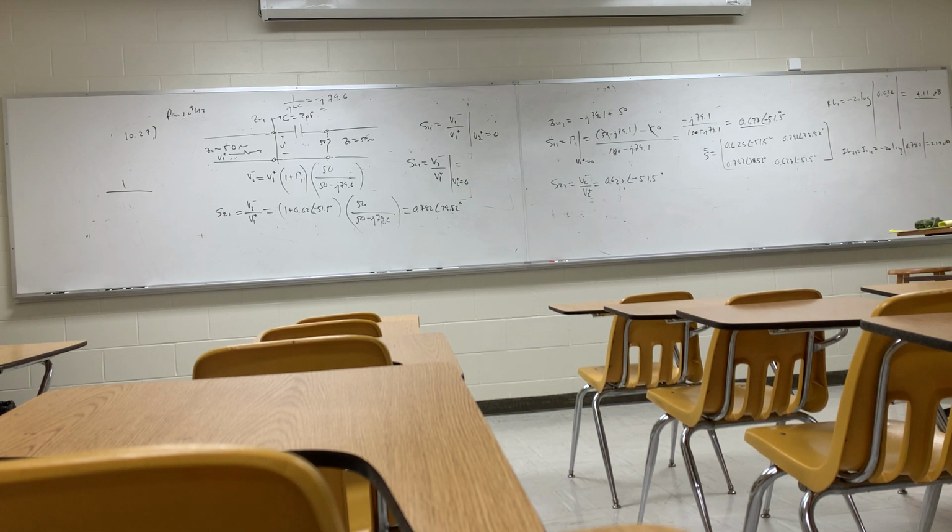Now go to the next one. That's B. Take a look at that. Is there any way that voltage from port 1 can get to port 2? Immediately you know S21 and S12 are 0. There can't be a forward or reverse voltage gain. Are you with me? Now, when you look at S11 or S22, look at that one carefully. What's the input impedance to port 1 or port 2? Infinite, right? It's an open circuit. You all see that? There's nothing connected.